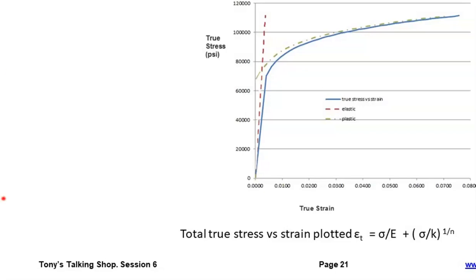Peter asks the question, which approach, low cycle or high cycle, would be appropriate for situations where there is a pretension present in the component which causes some local yielding, on top of which the service load is added, causing alternating stress in those yielded spots. I have in the past run a nonlinear analysis so that the local region does see regions of local plasticity.